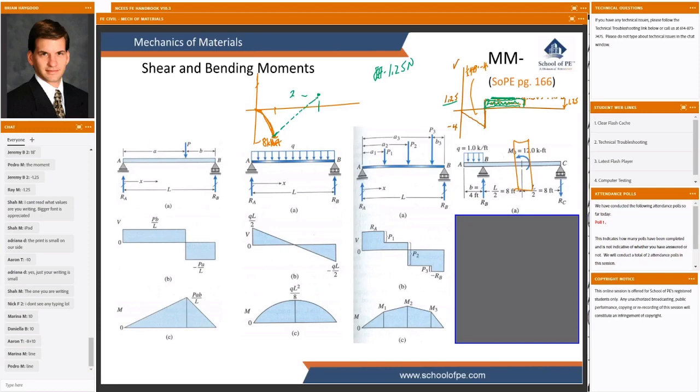All right, let's start at the right-hand end, and I'm pretty sure we've got nobody twisting the right-hand end off, so let's start our moment diagram at 0 there. And on our way to the right-hand end at 0, we'll be adding this area in blue. What's that value? Well, that's another 10 Newton meters. So to get from the 12-foot mark to the end of the beam, we're going to add another 10 to get to 0, which means we must be down here at -10.